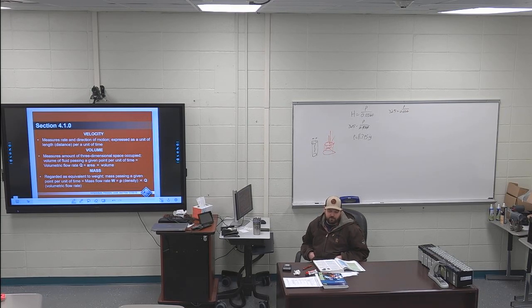On page 33, first full paragraph, first sentence is an online test question. Turbulent flow, as shown in B, is erratic instead of smooth or streamlined. So for you guys doing the trainer right here, if I had turbulent flow coming through that pipe, and you've got that paddle, like you saw the picture of the inside of that flow meter, and it's just a little paddle wheel flow meter. If I had turbulent flow in there, that paddle wheel is not going to spin the same as it would if I had laminar flow flowing through it. So it's going to mess up my reading. So it's important to have laminar flow.